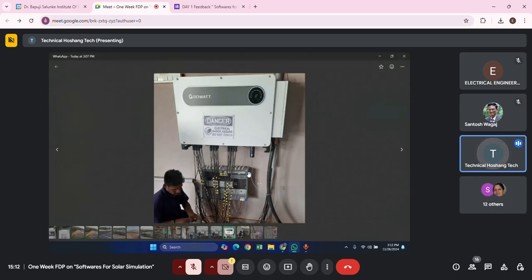You see a small cable coming. This is the data cable which we were using for the zero export function. So we were independently running almost half of the solar plant for the college. This data cable used to inform the inverter of the current load, and the inverter used to send the proper amount of current which can run the whole college.